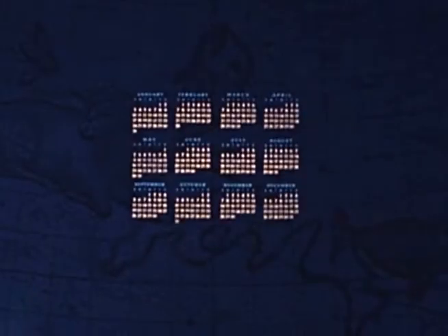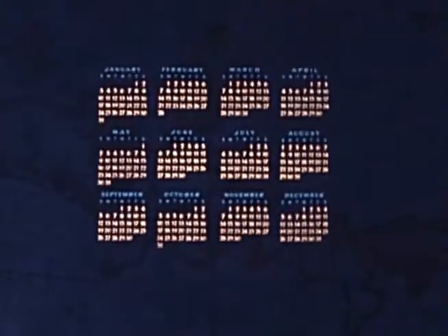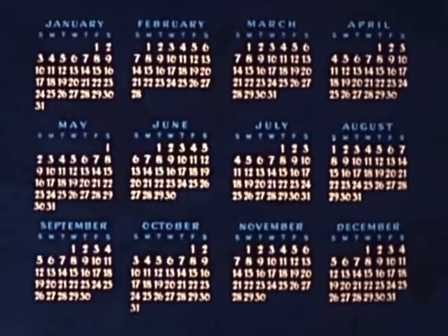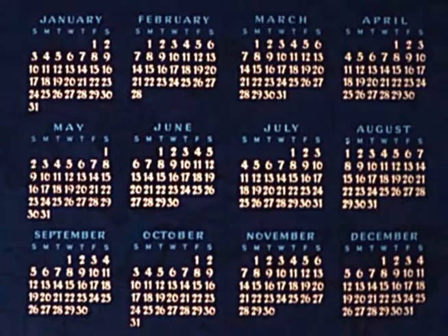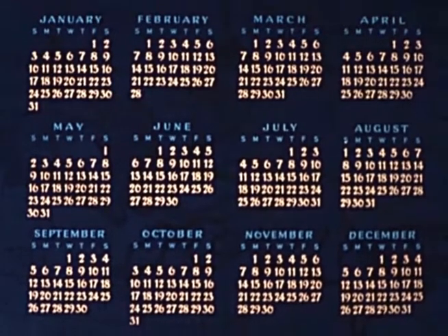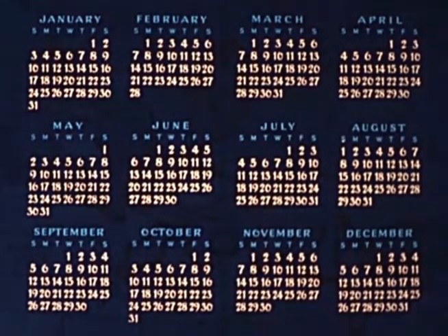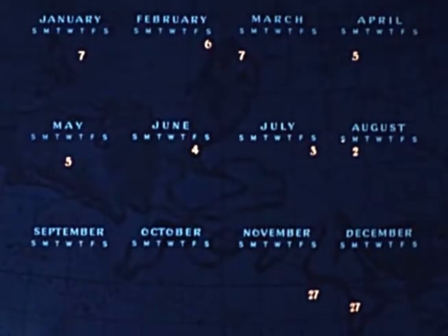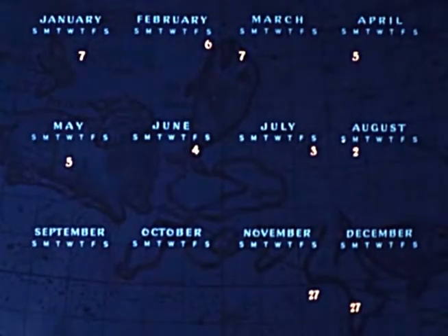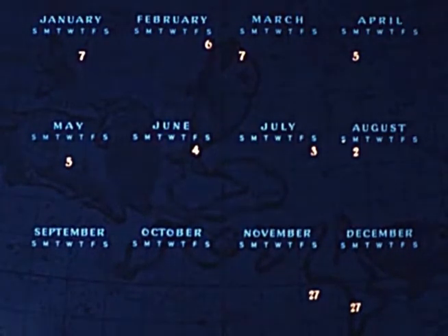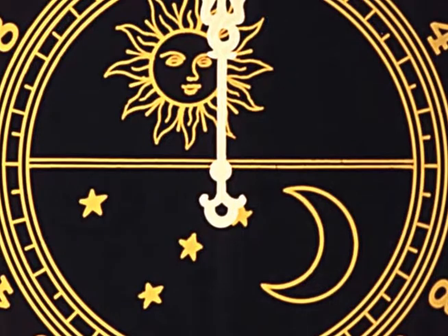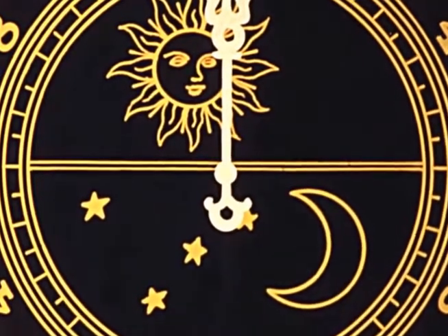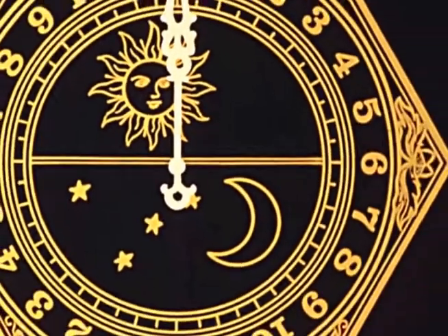To see how constraints limit launch windows, let's look at the days available for an entire year on which a lunar mission could be launched. If only a single landing site were available on the moon, all days but these would be eliminated. The determination of the time and duration of these launch windows is the subject of this film. We will first examine the daily window, the hours during a day when we can launch the lunar mission.